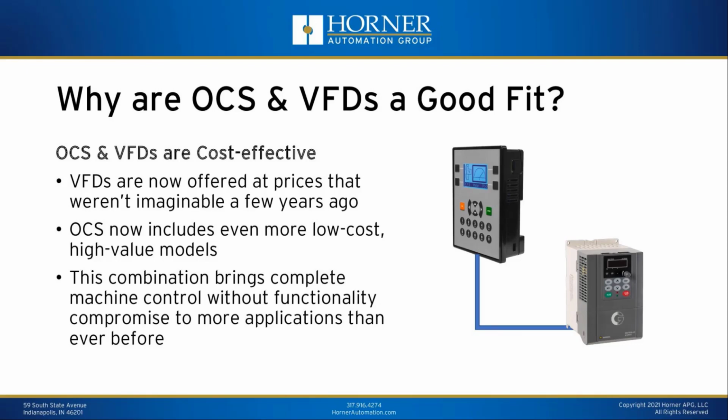It's got 30 I/O built into it, complete control capability with a modest operator interface built in, and the ability to connect and control a variable frequency drive over RS-485 and still do advanced features like data logging, for instance. So from a cost standpoint, again, another good match between the two.